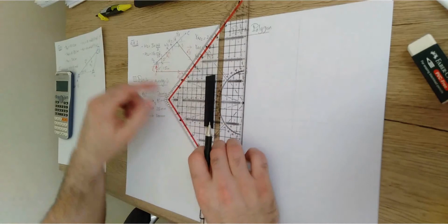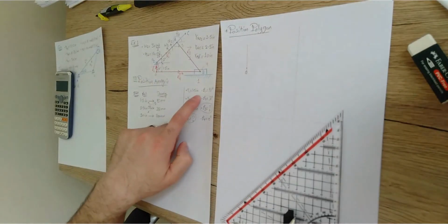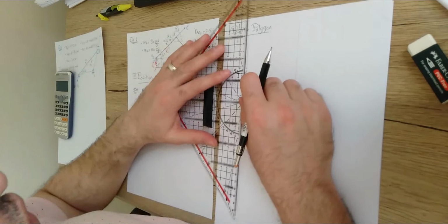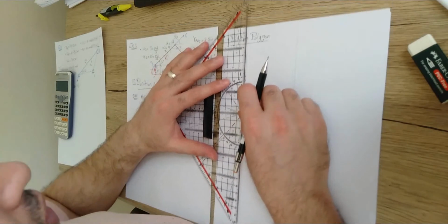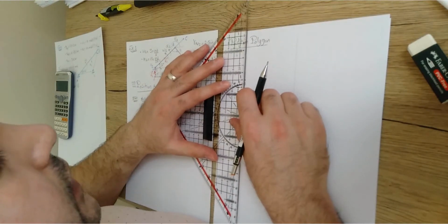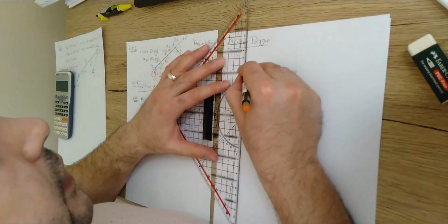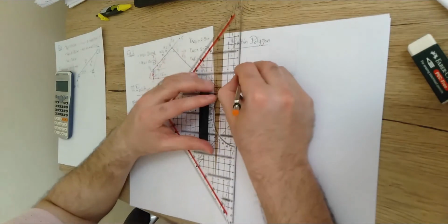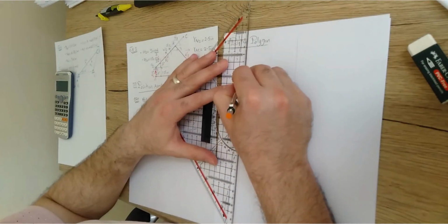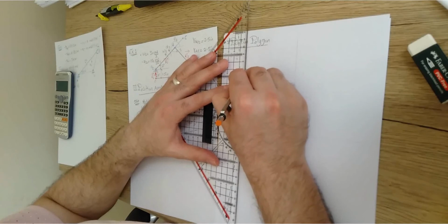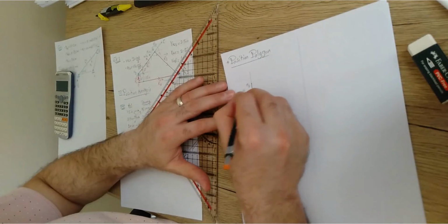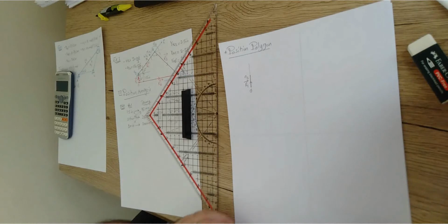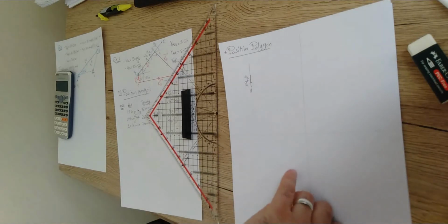Over this line, I'm going to measure the length of R1, which should be 1.5 inches, represented by 15 millimeters. So I'm going to measure 15 millimeters over this line. Mark a point. This should give us the O2 point. And then if we go over this line again between these 2 points, this should give us the position vector, the first one, which is the R1 vector. Make sense? So we got the first position vector.